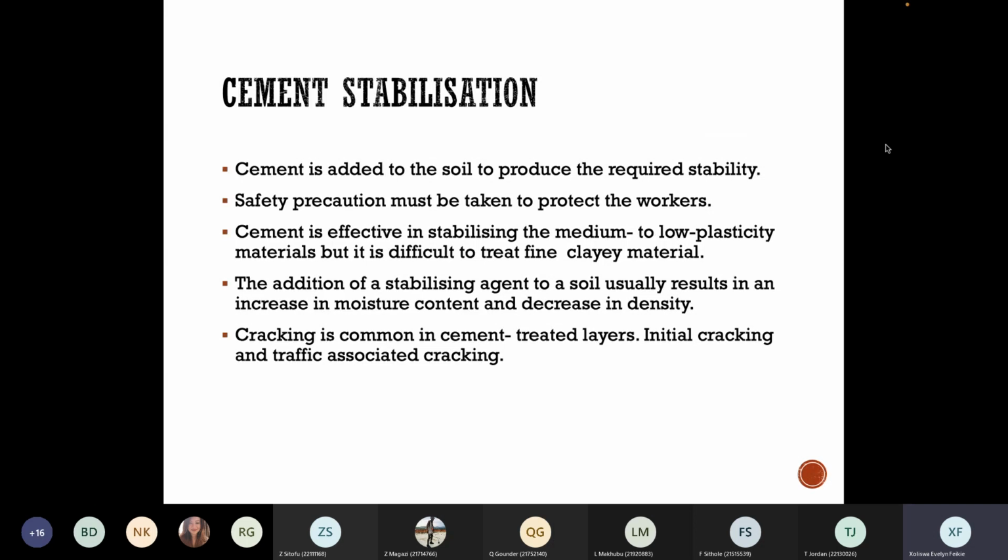So when you're reading it in the book, please remember to give more attention to that, because cement will hydrate, or the hydration process. What will happen is it will heat up, right? And if it's not cured, what will happen is you will have a rapid hardening, which will lead to the cracking.